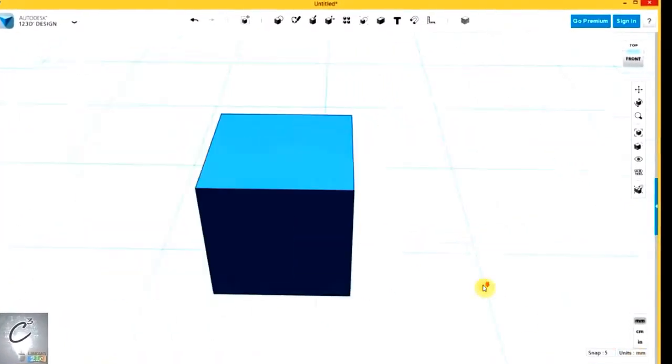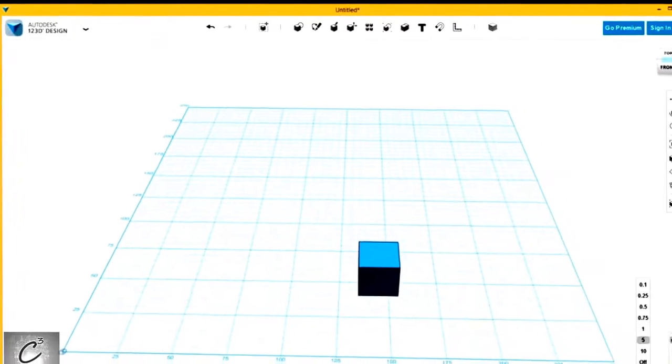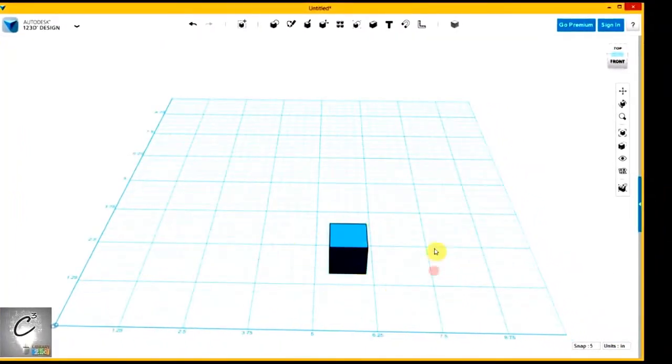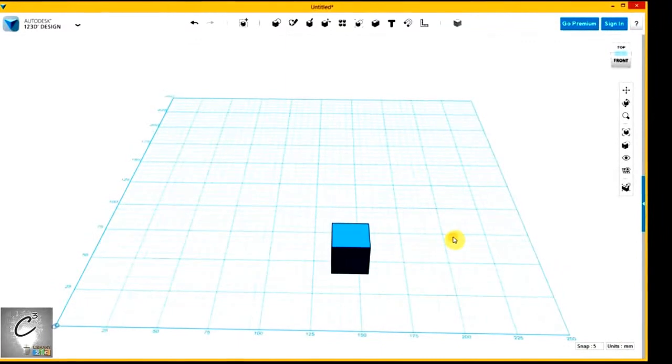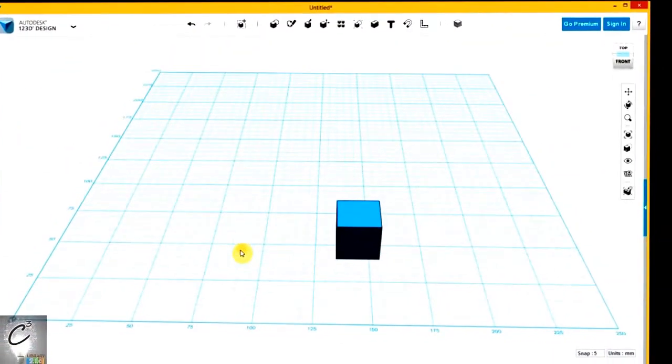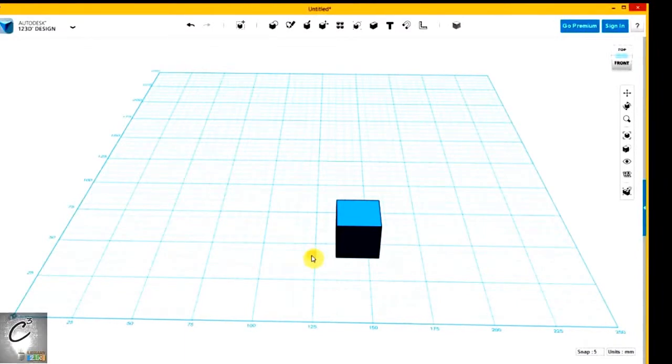You can edit the units that the grid is subdivided by into centimeters and inches, and it'll automatically convert the size of the object to the new measurement. Now, if you're a Pikes Peak Library District patron and you're doing this mostly to get some 3D prints going, I recommend you design in millimeters or design in inches and then convert to millimeters at the end.